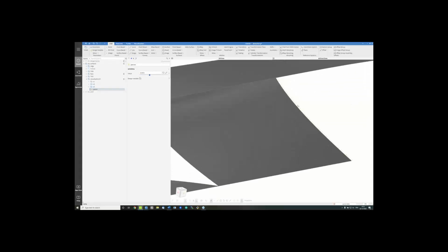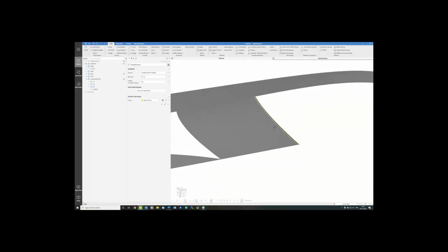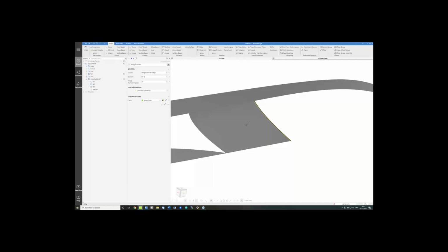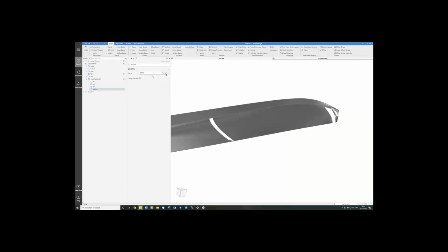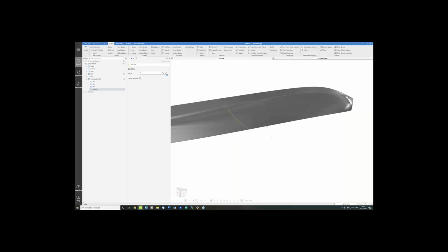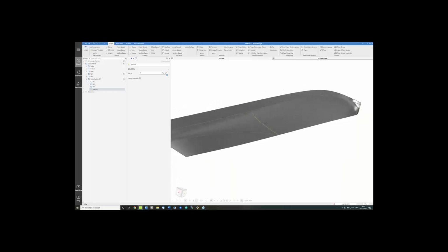Each of these sections has a parametric description, such as the angle towards the flat of side, the angle at the keel, maybe the sectional area is constrained. And we provide that information in longitudinal direction so that when we create our meta surface based on that definition, we can close all the gaps and make up the complete hull.